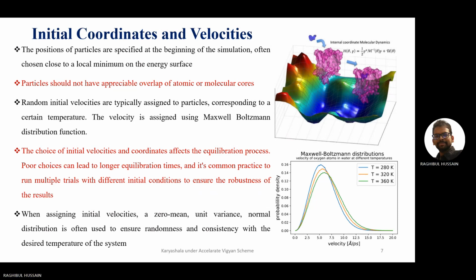It's a common practice that we do not take the output from a single simulation. We start our simulation, at least for any kind of thing, in triplicate. That means from three initial configurations we start our simulation, get the result, that means the trajectory result, get the final observable data, average it, and do the error bar.